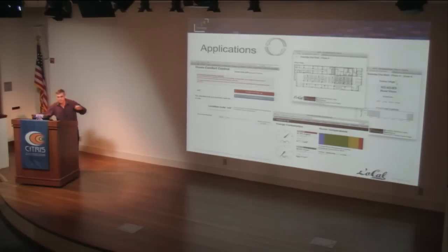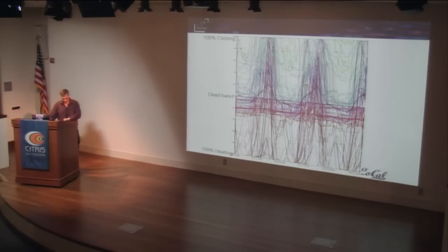Some of you got a sense, many of the folks in this building now have direct personalized control. There are special portals for the building, extensions of the building portal that Domenico sees, that feed that information back. As we've done things like static pressure resets and whatnot, we've actually been able to observe how people perceive that by where they inserted the overrides and so forth.